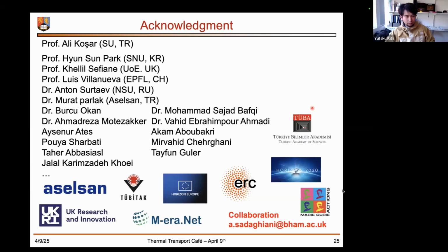Thank you. I have a quick follow-up question. Now that you mentioned Cassie Baxter and the micro nanostructures, that means you're basically using some trapped air in micro and nanostructures, right? But in many phase change heat transfer applications, you assume that the liquid is degassed. So you want to operate with fluids without any non-condensable gases. So how would that be practical in that kind of situation with your substrates?